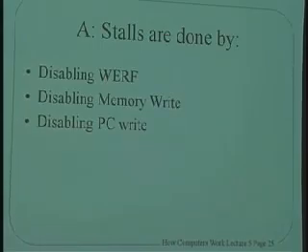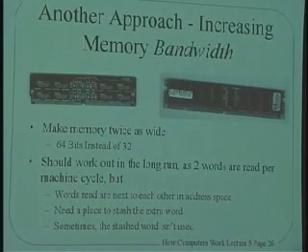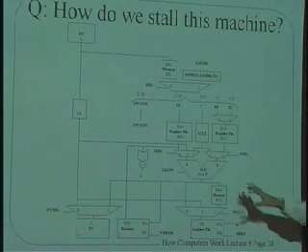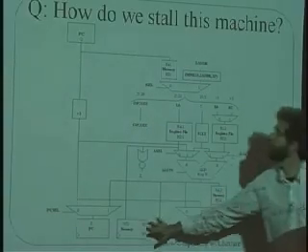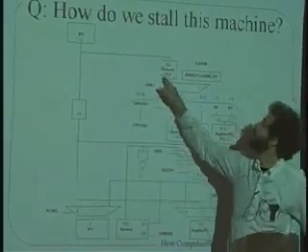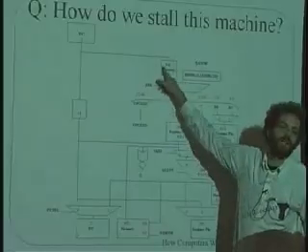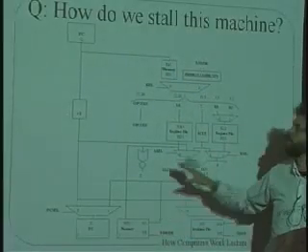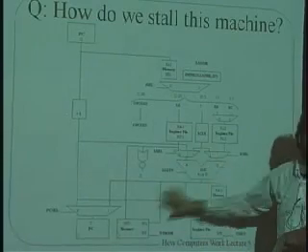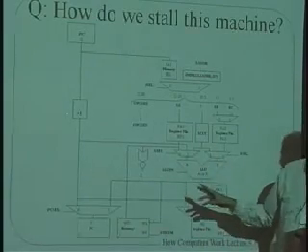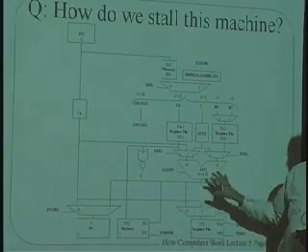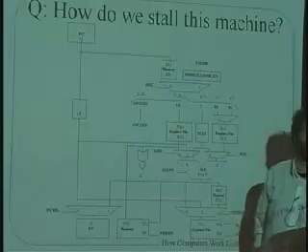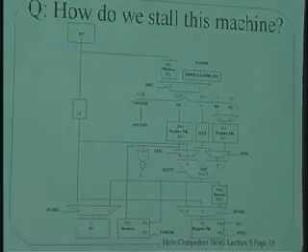So architecturally, everything looks like it has multiple ports, but in fact, we're going to fake the fact that there's 1, 2, 3 ports here by having this be the one that's used most of the time. And if we ever need to use this one or that one, we'll stall the machine and finish up our work on the other 2 and then pick up from where we left off, because it's a big memory, and we don't do this very often. Those are loads and stores. Okay.